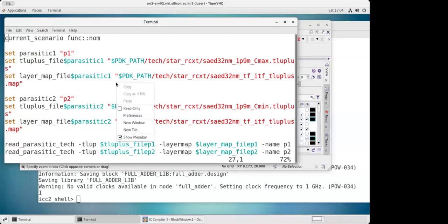Resistance R equals rho L by A, length, width, everything is going to change, so your resistance is going to change. So what will happen if your resistance and capacitance change? Your delay is going to change, everything is going to change. For that also, the foundry is telling that the variation can be 10% on the plus side and the minus side. That's where the precision comes into the picture.